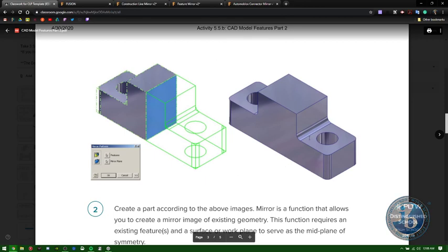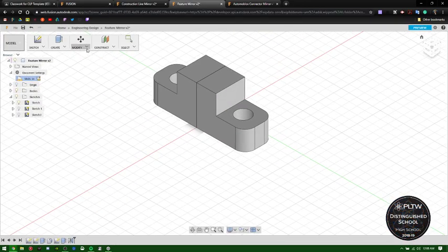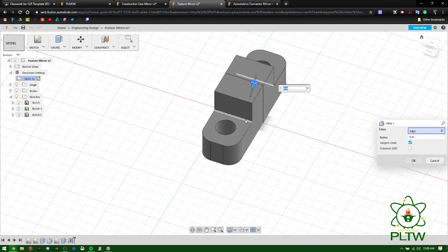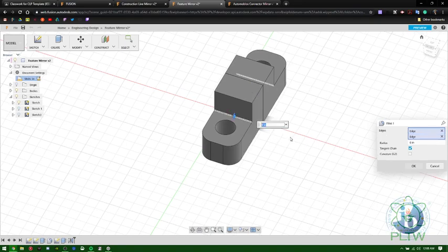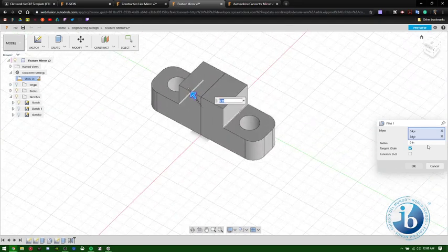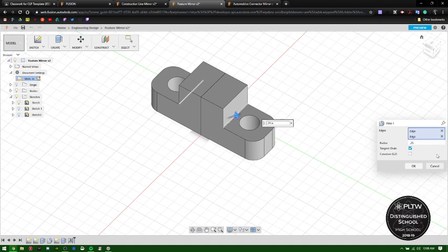Go to that piece. Looks like there's a 0.25 fillet in here as well. I don't want to miss that. So I come over to modify again just to show you fillet. Just want that inside edge as well as this side edge. And again, hard right click, hold right click, I should say, to rotate like this, as you can see going around. Makes it a little easier. 0.25 is the radius.